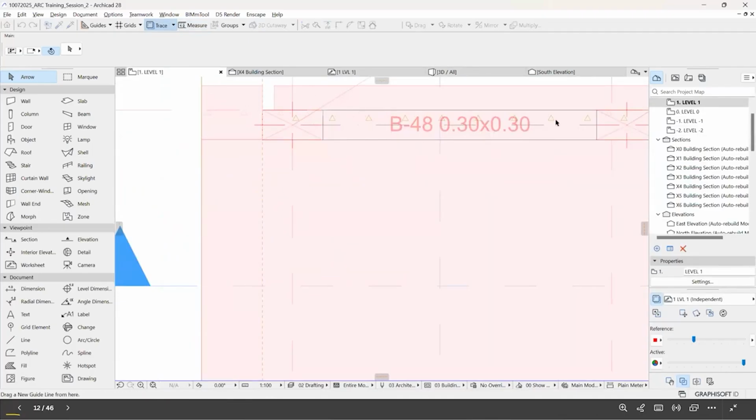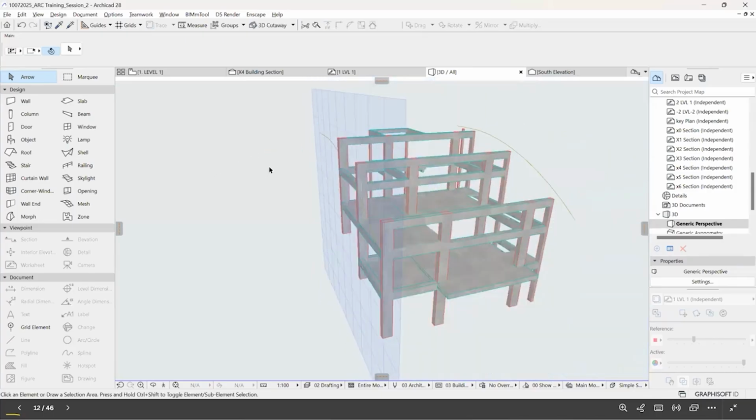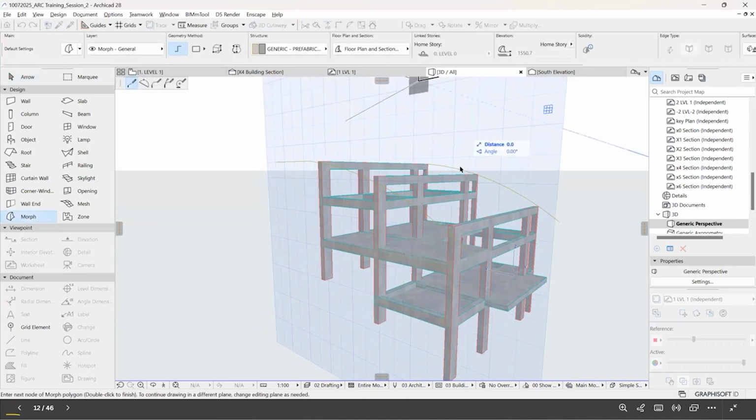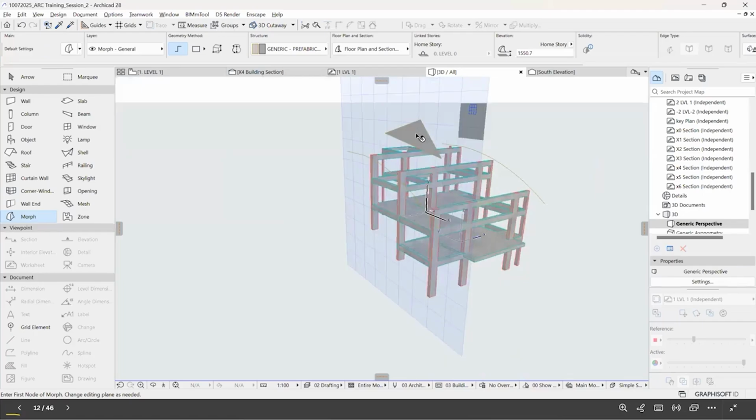In 3D, I could make use of the same tool, use the offset option, and I can probably snap it as well to this. Now you can see I have placed a working plane here. This is one of the ways that we put the working plane, but I'm just showing you what exactly the plane is. If you have the plane ready, whatever I do here on the space will be on that working plane instead. This is something that most advanced 3D modeling software does, this concept of working plane, where you set up the working plane and you start modeling on top of that.